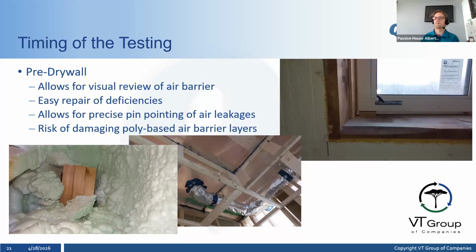So if I'm doing a positive test to do the ACH, that's what I'm going to do next. And then I turn on the camera, and then I depressurize the house, and then I typically go to the lowest risk assembly, the lowest risk floor first. So if that's a conventional house with a batten poly attic space, I'm starting on the top floor because there's not a lot of leakage that I'm going to see with my thermal camera that I wouldn't be able to see visually, right?